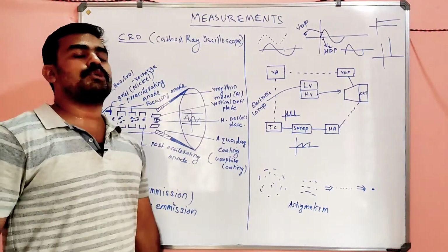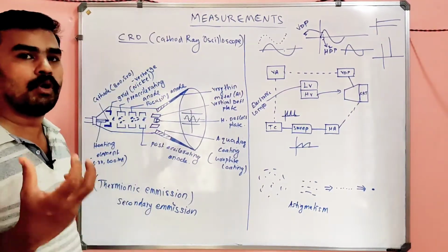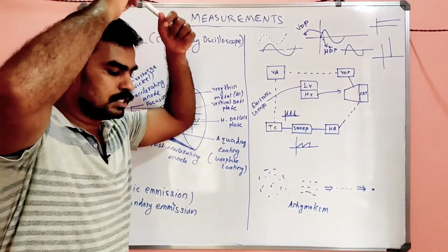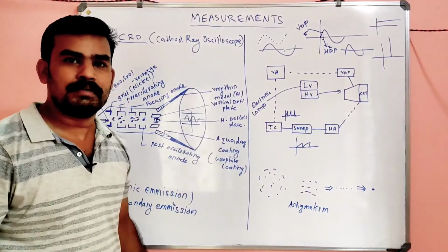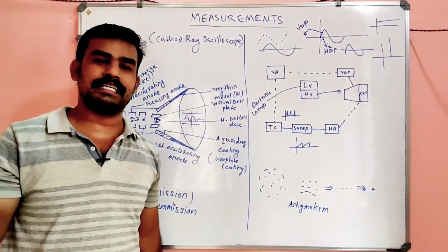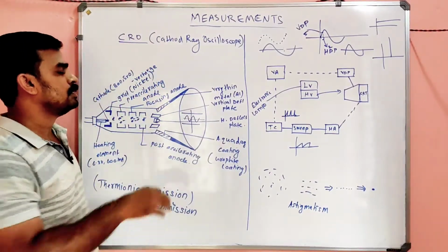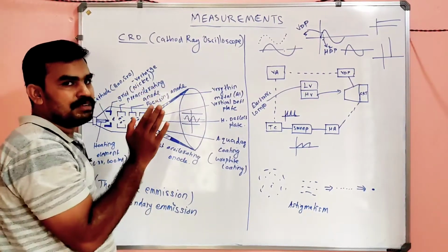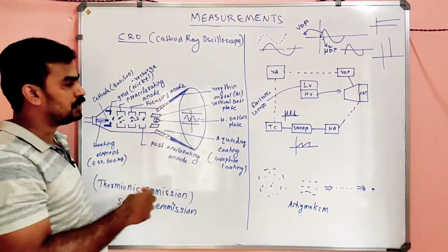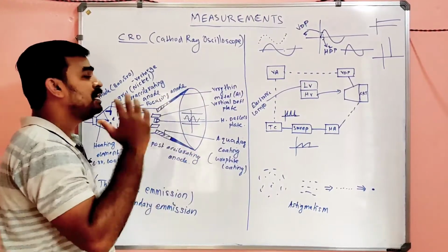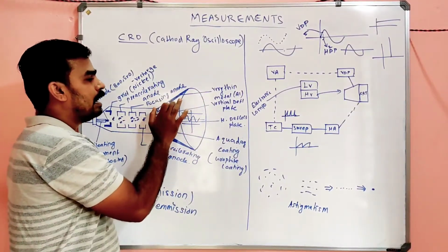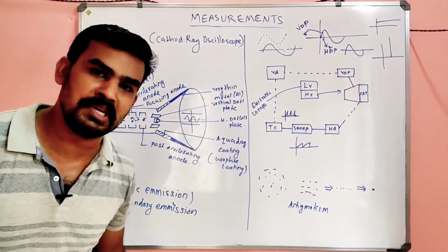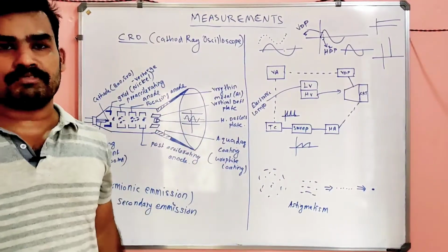See, suppose you throw a ball or some small paper balls into the water. Some of it will be absorbed rapidly, but some of it will be rejected back. The same thing will happen here also. Some electrons will be absorbed here and some will be ejected from here. That absorption is called secondary absorption, and that emission is called secondary emission. Anyhow, the absorbed electrons are fewer compared to the ejected electrons from the aluminum, so a larger number of electrons will be created.